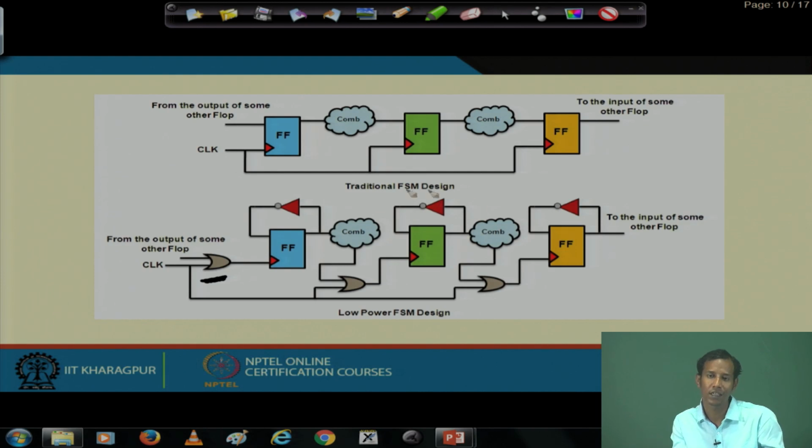If the FSM is in the running condition, then according to the logic which provides the corresponding enable signal from this combinational logic, it will be ORed with the clock. So, whenever this enable signal is okay, I need that enable signal to make the clock enabled and it will be running in the running condition.